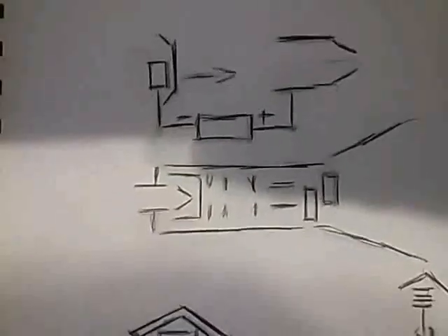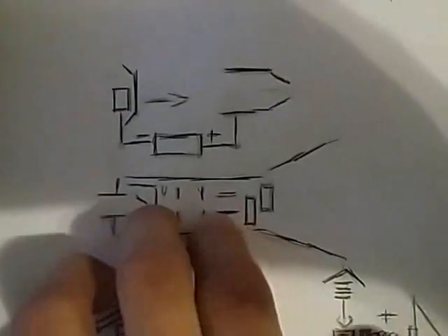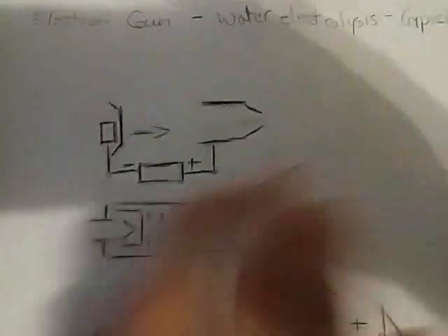Now, when I say it's going to shoot electrons, people would think, oh man, that's too high tech. No, not really. An electron gun is a very simple device. It's basically a heater, an anode, and a cathode. You got basically one cathode and two anodes and a heater. That's it. The heater is basically the source. This is basically a simple electron gun, or CRT. They're in every cathode ray television that ever existed. Basically, there's a heater, a cathode, an anode, and an anode. And you're going to basically direct it with directing plates. The plates are going to help it direct the electrons straight to the picture tube, okay?